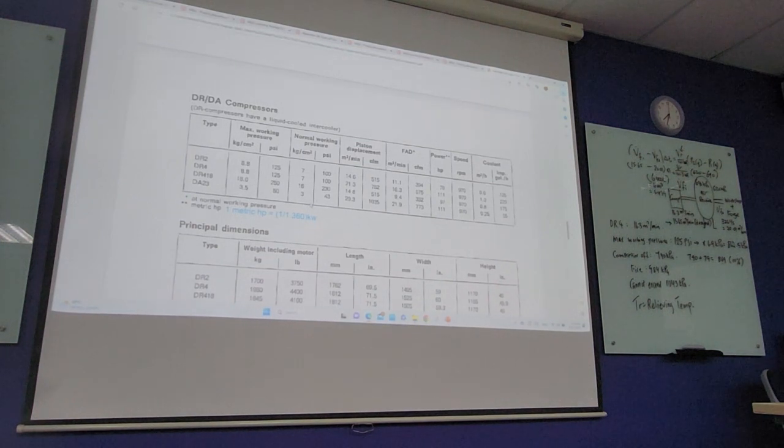Okay, yeah, well, then you see the spec. It's a bit higher. If we choose the lowest, which is a bit higher, it is 16.3, it should be 25. If let's say 25, you do not need a receiver. But our question asks, we want you to design a receiver. So you have an average demand need, but when it comes to surge, you still have a receiver to cover. This one, because it's too powerful, we don't need to have a receiver. The contractor can supply sufficient. But because our maximum is 20, right, that's what you mentioned. Yeah, but not 25. So it's actually the cost you put in here.